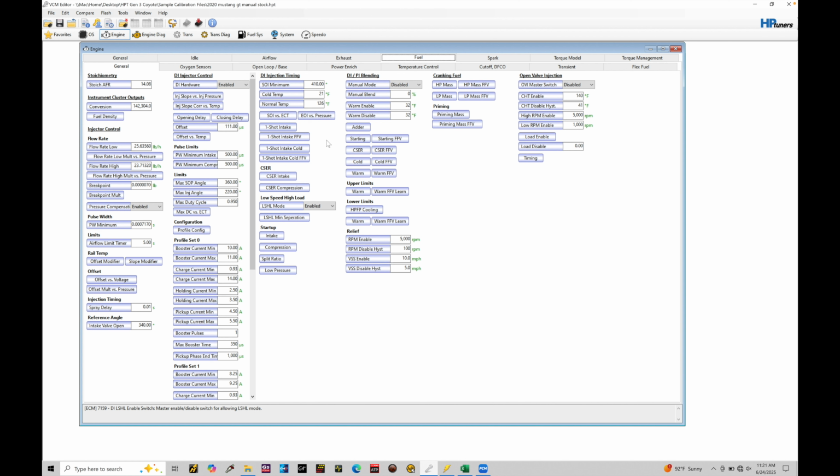We also have our DI PI blending. We'll talk about this more in the next tutorial, focusing on more of the port injection and how it works in this particular Gen 3 application, and then the blending that's going to happen between those. So we'll cover some of our table and programming in here. We also have, in conjunction with this, some other things related to our GDI system.